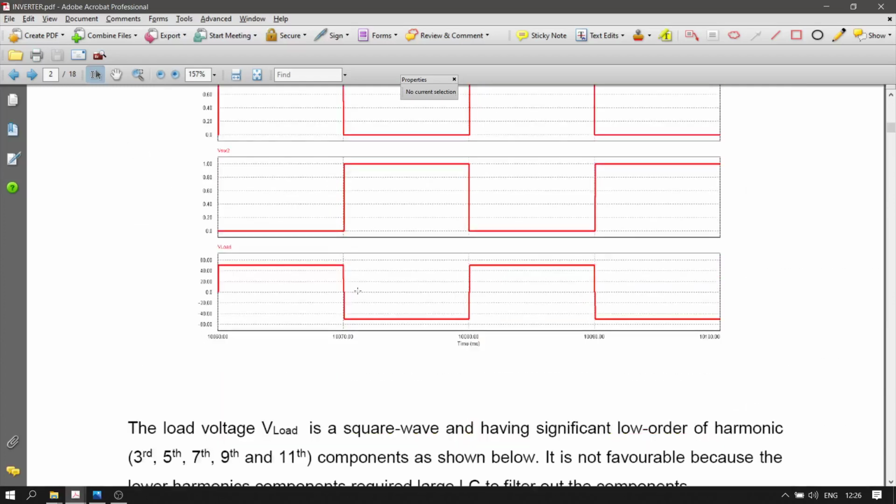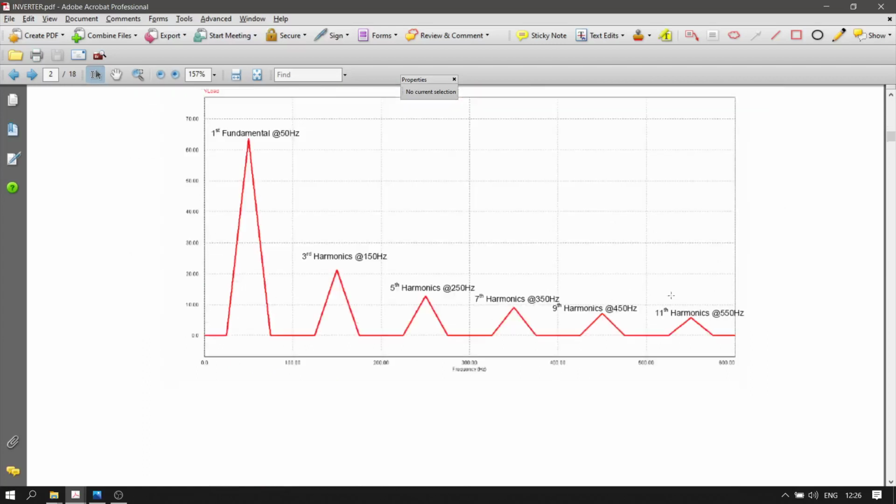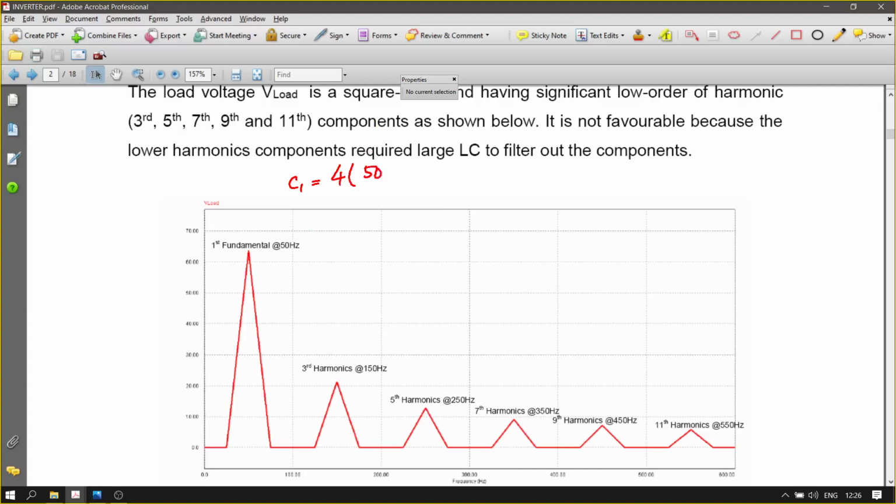So if you solve using that previous note on the square waveform, then you'll be able to get all these components here, and also you can calculate the amplitude here, as I just showed you. So for that first component, C1, before this we have IDC, but now we have 50 volts. 50 volts times 4 over 1 pi.